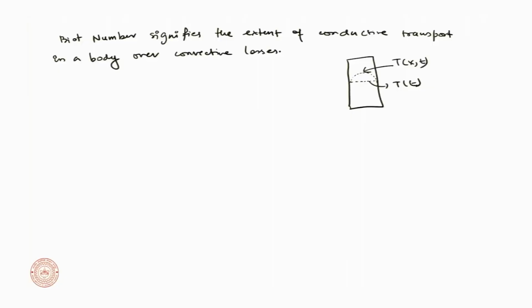So, larger Biot number bodies are poorly conductive, which means that the heat from the center will need to face some resistance to dissipate out, right. So, the center might be at a different temperature compared to the surrounding. However, if a body is highly conductive, then whatever heat is being generated can quickly go out from the body. So, in that case, there is no spatial variation, the temperature throughout the body is constant, there is only temporal variation, right. That is the significance of Biot number.